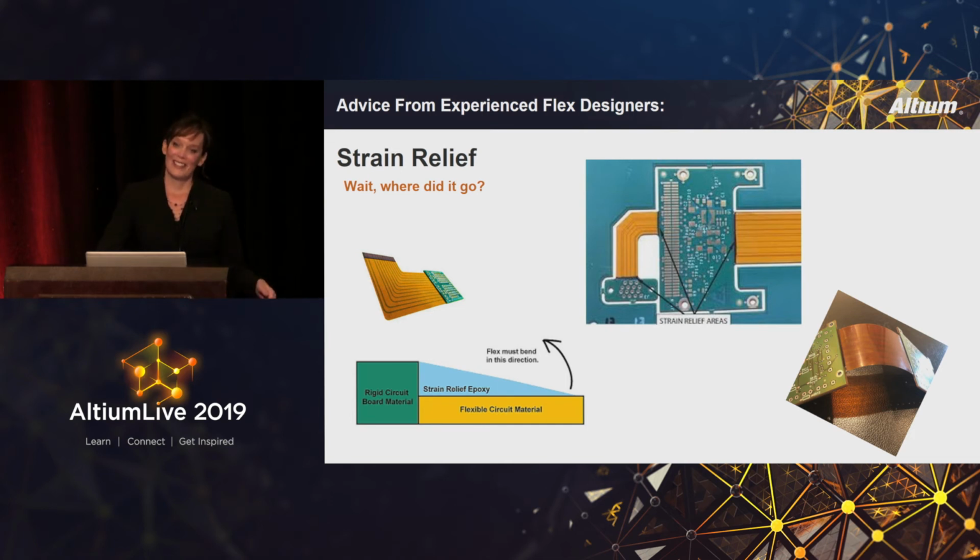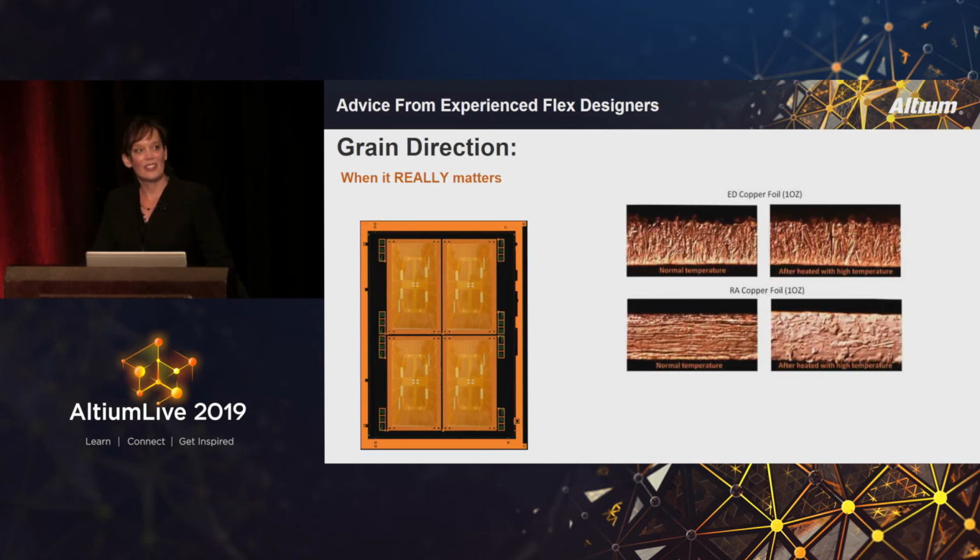Somebody did tell me a cautionary tale when we were talking about this, though. They happened to have an outgassing requirement that exceeded the NASA spec and started having to research materials to be able to use a different type of EcoBond. They did that, it was applied, ran through assembly, and it just disappeared. It completely wiped off the board. So what they had selected was just not compatible with the assembly process. The cautionary tale was make sure when you're looking at new materials that you're looking from start to finish and take all of the processes into account. Did also mention that if you have this epoxy on there and for whatever reason you do need to remove it, if you soak it in isopropyl alcohol long enough, it'll come off.